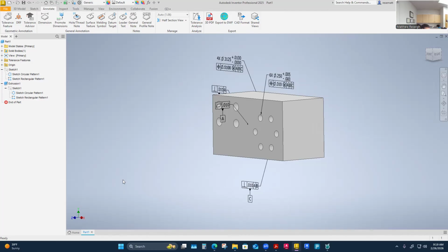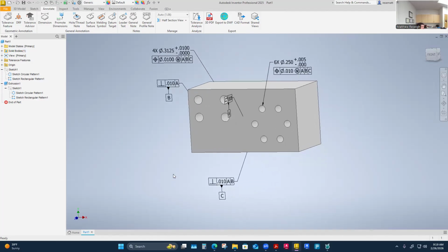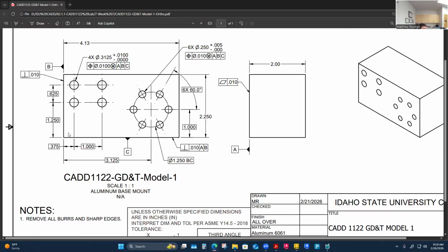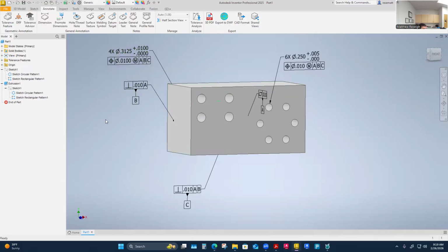My question next would be, do they like us to put basic dimensions on here as well? Because we could basic dimension these. What that would look like is, if I look at my drawing, in my quick little wrap up here, let's locate one of these. These two dimensions would definitely be basic, 1.25 and 0.375. They're in my sketch, but in true model part definition or model based definition, I can add a dimension here. I can say from this hole to this surface.